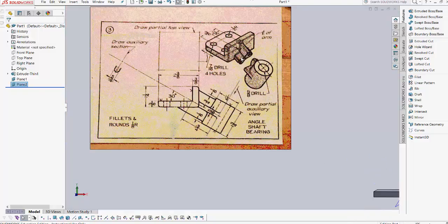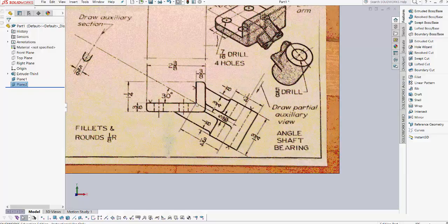So the cross comes out and is tangent to that cylinder. That means the cross ends right down the middle of that cylinder. And so what we're going to do is draw the cross out here on plane 2, and extrude it backwards up until it hits our L-shaped base. A lot of students want to draw it on plane 1 and extrude it out towards plane 2, but you don't get this little tail then.